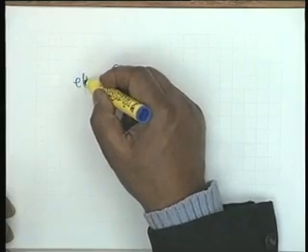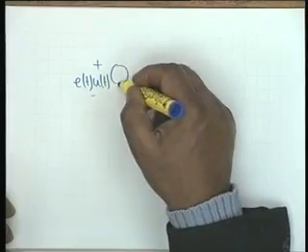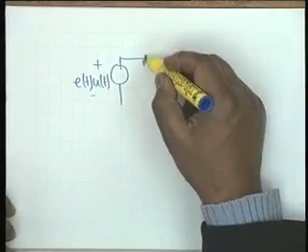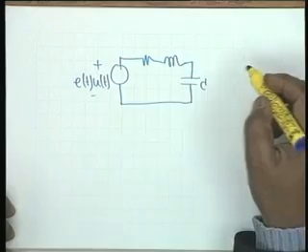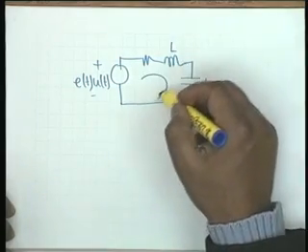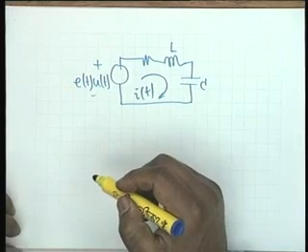For an inductor, the voltage is L dI/dt, whereas a capacitor voltage is the integral of I(t) dt, and therefore if I differentiate once more I shall get the second differential coefficient of I(t). And the example that we shall take is one which you shall come across again and again, that is, we consider a voltage source E of t u of t connected to a series combination of resistance, inductance and capacitance. And the problem is to find out the current I of t.